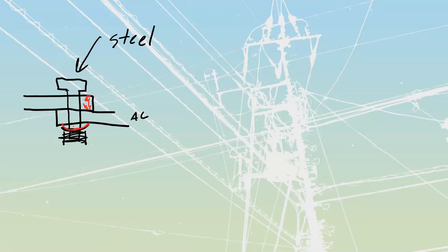Power factor correction, we have talked about numerous times. We're just going to gloss over it at this point over here. We know what our limits are going to be for power factor. We're usually looking for a 90% power factor or greater. We want our power factor usually to be greater than 90%, but we want to try and keep it below 95% if we can.